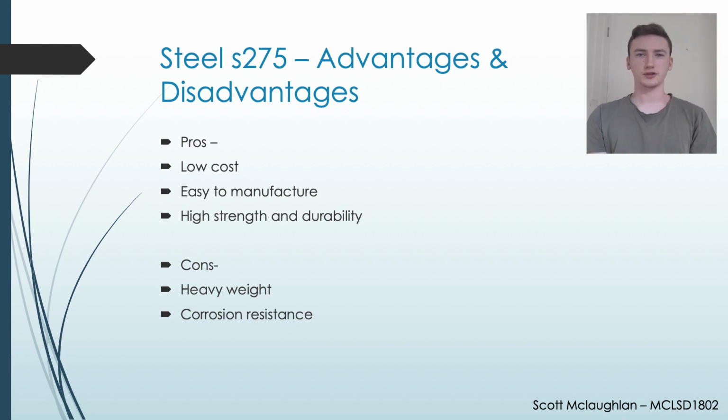Steel is cheap, extremely durable, extremely fatigue resistant, simple to repair, and simple to use. Unlike carbon fiber and aluminium, it is usually easy to repair any damage done to the steel frame. Slightly surprisingly, despite its strength, thanks to its elastic characteristics, steel provides excellent compliance rates. The downside of steel is that it is prone to rust and imposes a weight penalty on other materials.